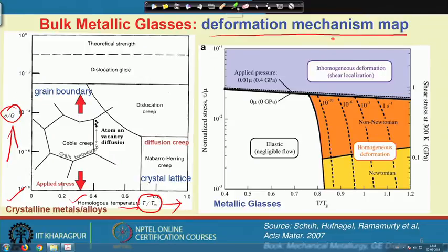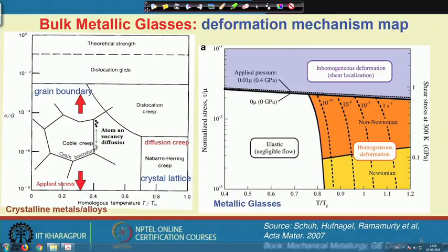Here we must know that the shear strain is basically linked with the shear stress, and maybe a little bit more clear, shear stress is equal to the shear strain into the shear modulus. So, if I simply make a ratio of the shear stress versus G, then I will get the shear strain. So, here you will see that there is a stress term and there is a G, okay, which is the ratio.